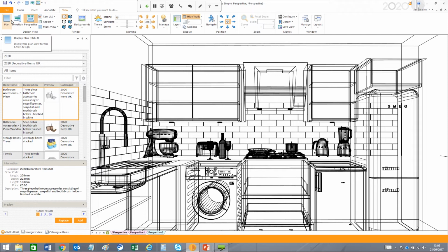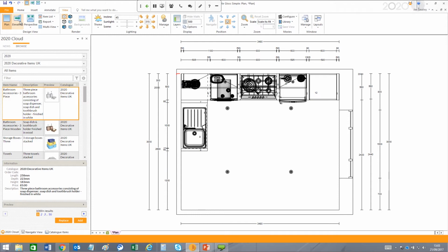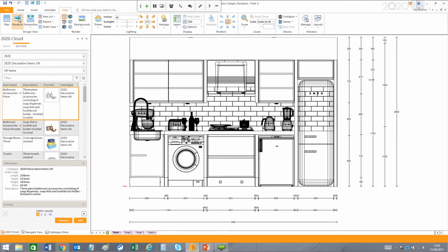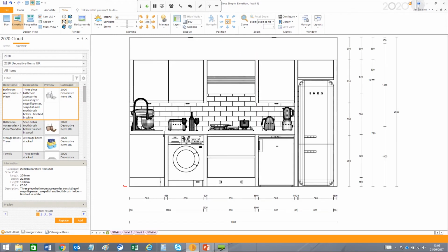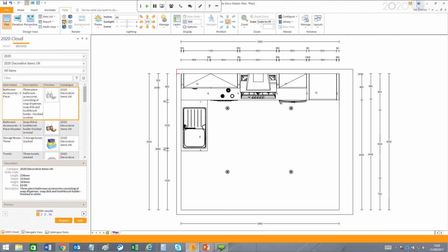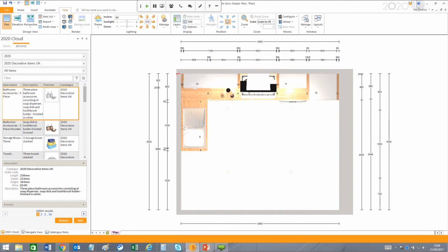So in terms of Fusion itself now, we have 6 renders, and those familiar with the version 5 interface will notice that we no longer have a gallery control. We have 6 elementary renders with very little need for configuration. We start off with a wireframe, which would commonly be used obviously in plan and elevation views. We also have a white fill, entirely consistent with version 5 and earlier. We have a color fill, and we have a draft render as well.